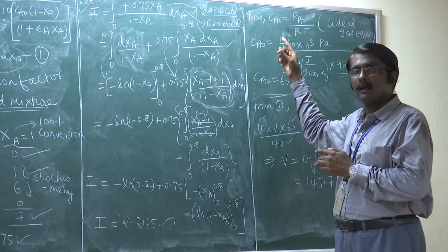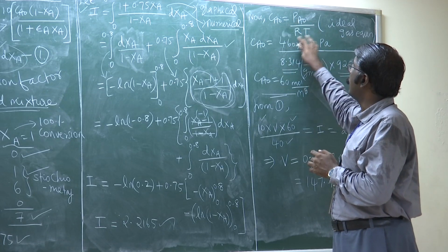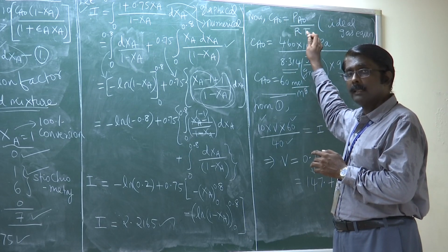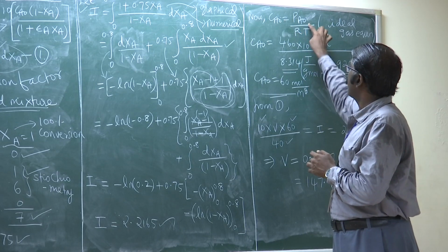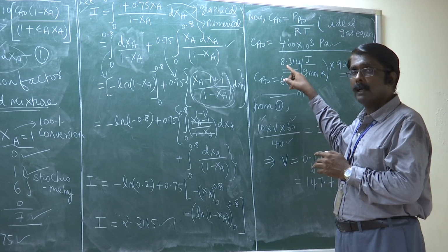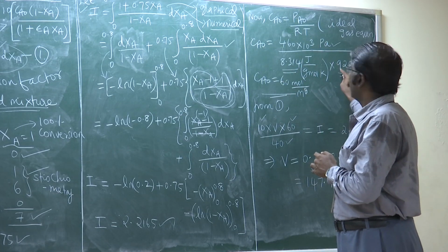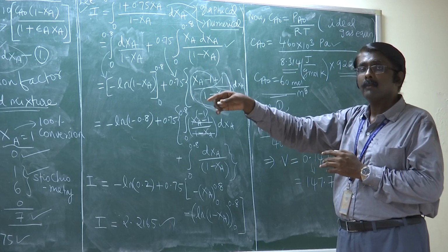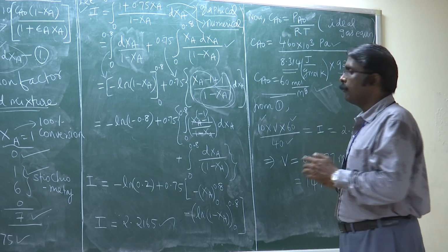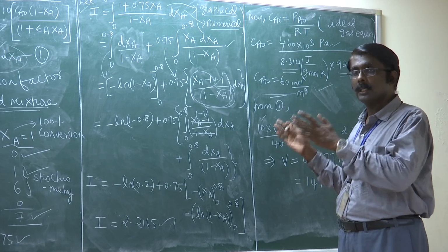So for ideal gases, the equation to be used is C_A0 is equal to P_A0 divided by RT. P_A0 is the initial partial pressure, R is the universal gas constant, T is the reaction temperature. The P_A0 value is given data. The R value in SI system should be 8.314 joule per gram mole Kelvin. Temperature value is 922 Kelvin, which is also given in the problem statement itself. Substituting all the values and simplifying, we get C_A0 as 60 mole per meter cube, the initial concentration of A.